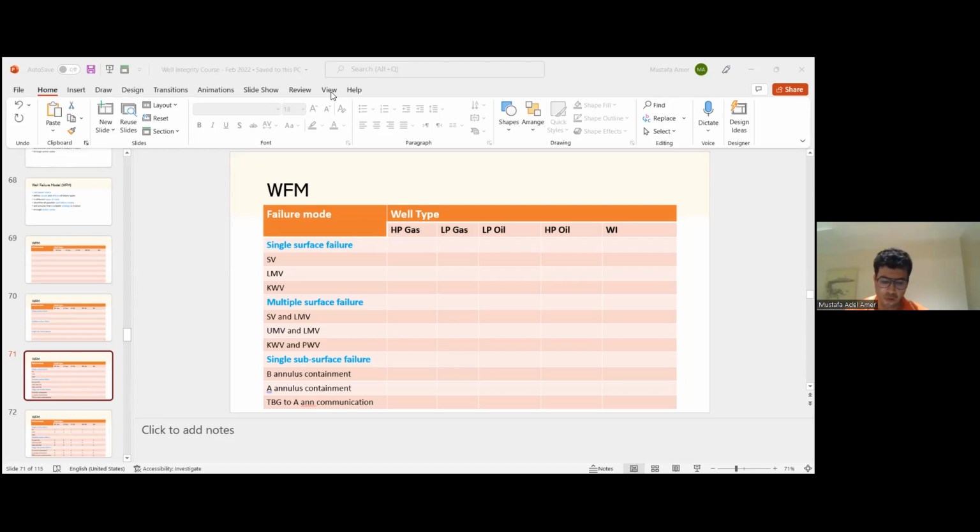For example, you go and perform your test. The well is fine. You don't see any pressures on the annulus or anything. And then you do your test in the B annulus, and you find yourself pumping. So you don't get anything. So your fluid that you are injecting is leaking. So you don't have completion fluid in the B annulus itself. So from these interactions with the well, your experience with the area, and the data available to you, you get to know these sort of things.